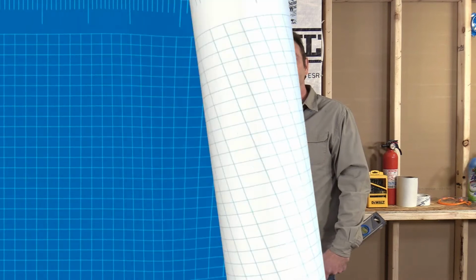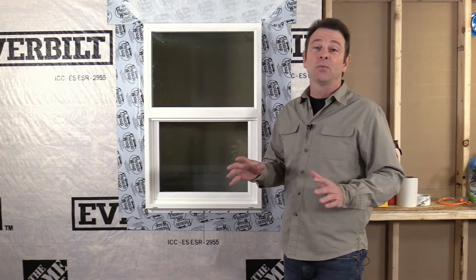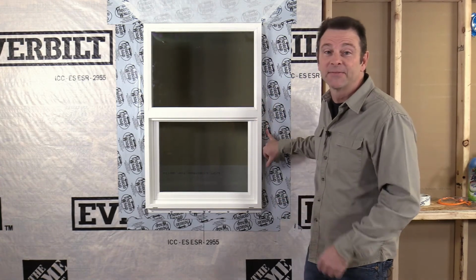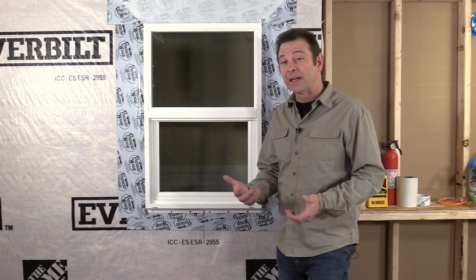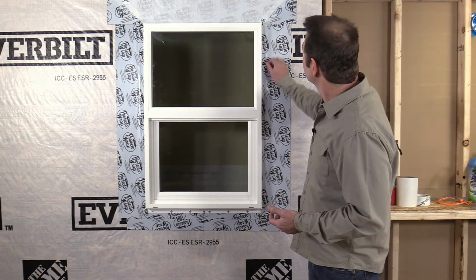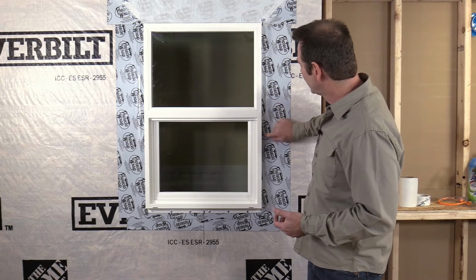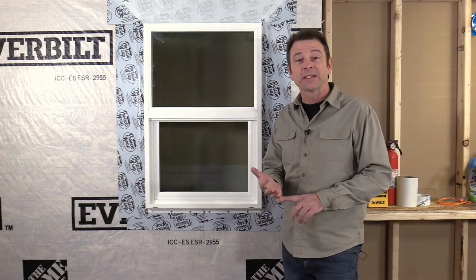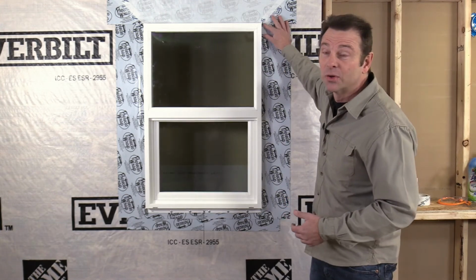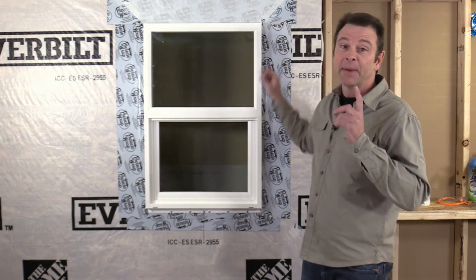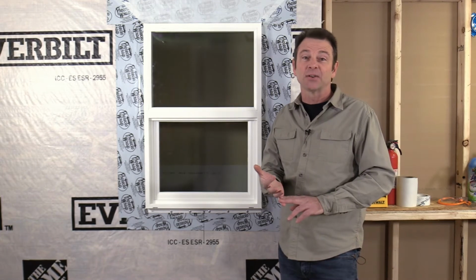So since I'm here, let's go ahead and talk about fasteners. Almost all windows, especially ones with nailing fins or flanges, will have fasteners in them. We need a lot of fasteners to put a window up, and there should be several fasteners all the way around. They will have specific spacing on the perimeter, and according to the manufacturer, they will give specific specs to stay off of the corners a certain distance. Make sure that you know what those two specs are.